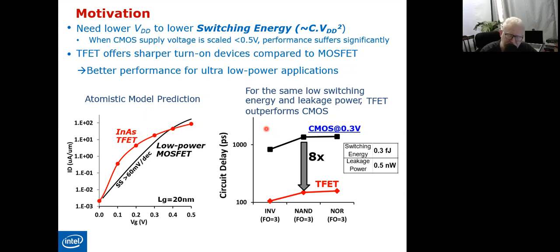Herein, when we focus on the phrase updated structures, we are referring to two parameters. Either to change the material, since usually we are using silicon as the main semiconductor material in fabrication. So maybe the first stage is to search for another material. For example, here we are using indium arsenide. We have gallium arsenide, we have indium gallium phosphide, we have what's called IGZO. We will talk about it later on in this lecture, and all other materials. So the first perspective is to change the material, and the second is to change the structure, to introduce a new structure like, for example, the TFET.